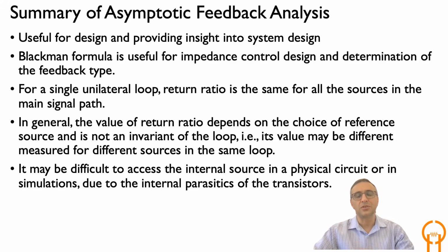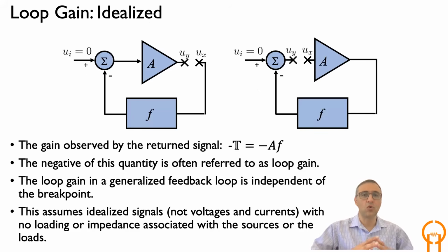And the other challenge with return ratio sometimes is that it may be difficult to access an internal source in an actual physical circuit, or the parasitics of the transistor if it's in a complex transistor model inside a simulator. So these basically lead us to another tool that we developed, which is the loop gain.